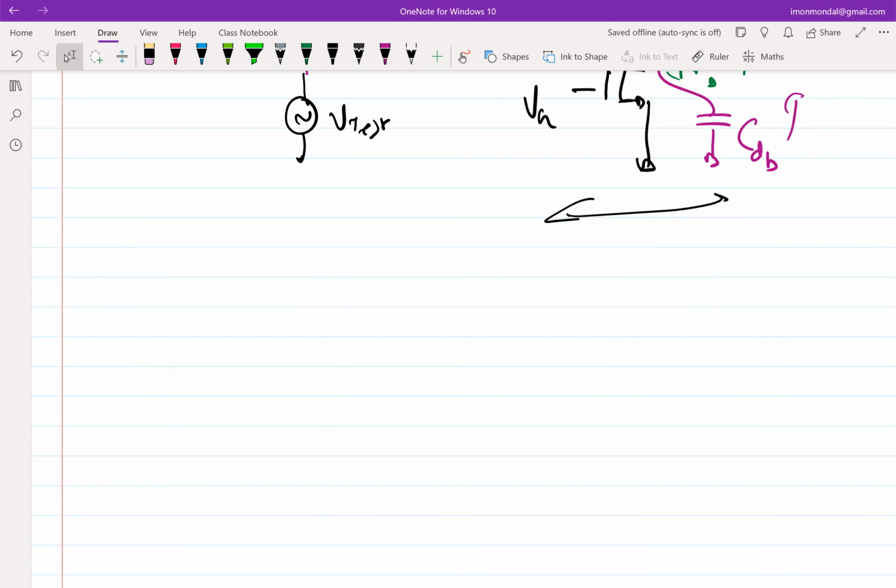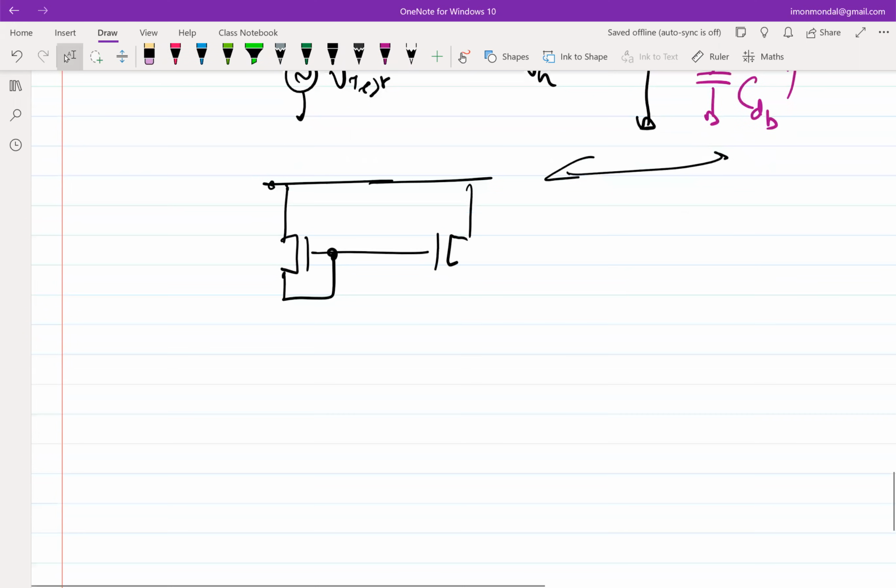So essentially, till now we have been dealing with the differential pair, but whatever we have seen is essentially another fancy way of making a common source amplifier. So the issues with the common source amplifier still persist. That is, you might not have enough gain. If you don't have enough gain, what do you do? You put a cascode, right? So the same thing happens here. If you don't have enough gain, you will have to do something about it. And cascoding increases the output impedance and can give us more gain.